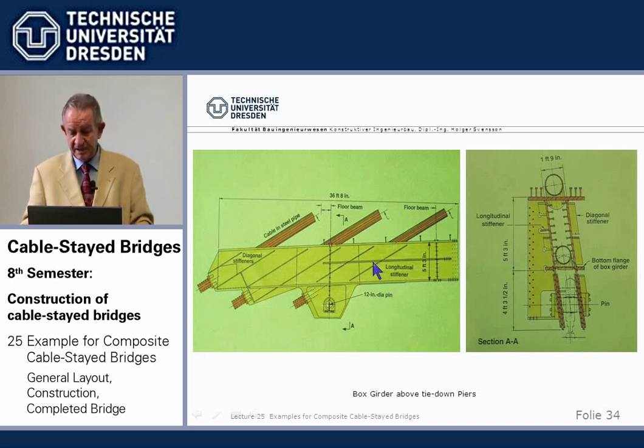So we have then at the end widened the plate girder to a box where the very strong backstay cables are anchored. It's connected to the pier here with a pin, and it's cantilevering out here. And because that's only, here we haven't done, 1 foot 9 inches.